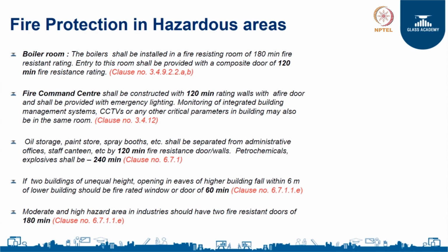So, again it depends on a case to case basis, but if you look at a typical application like a residence, you see application in lift lobbies and exit stairways. If you look at a hospital, it is going to be ICUs and operation theatres. If you look at a metro station, it is going to be kiosks, control rooms and machine rooms. If you look at an industry, it is going to be hazardous areas, boiler rooms, storage rooms. So, again the applications are different based on how the fire could occur or how fire could spread in each of these applications. The duration of protection changes.